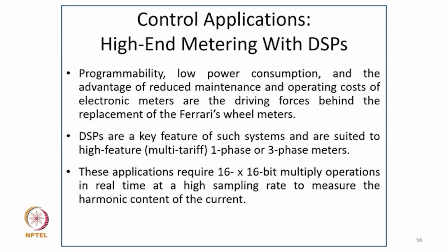And coming to typically high-end metering with the DSP, programmability, low power consumption, and the advantage of reduced maintenance and operating cost of electronic meters are the driving force behind the replacement of Ferraris wheel meters. DSPs are the key feature of such systems and are suited to high-feature multi-tariff single-phase and 3-phase meters. These applications require 16 by 16-bit multiply operations in real time at a high sampling rate and to measure the harmonic content of